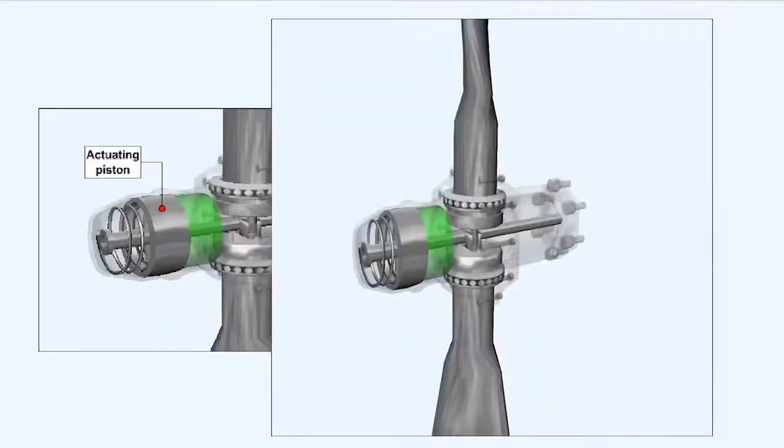Although mechanically or electrically actuated pitch change mechanisms are in use, the hydraulic method is the most commonly used. The system utilizes oil from the engine or reduction gearbox lubrication system as the source of hydraulic pressure. In this system, the pitch change mechanism is operated by a piston moving under the influence of the oil pressure.